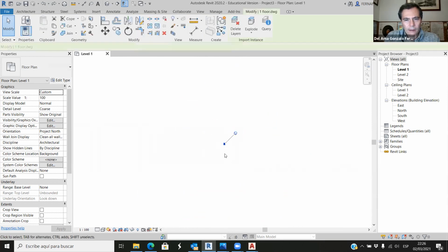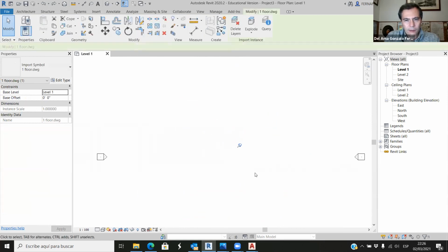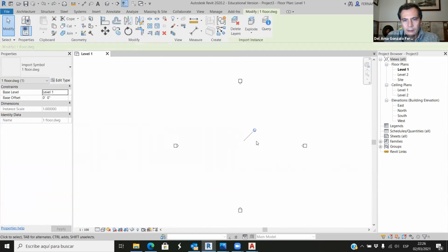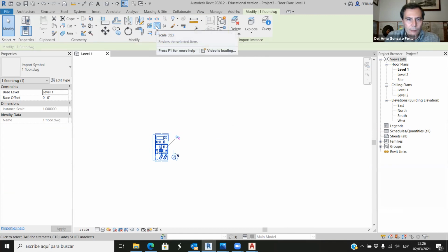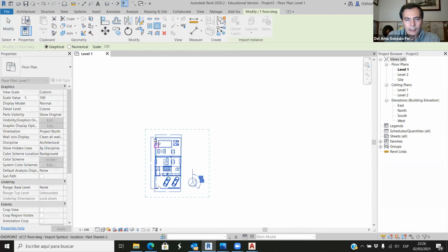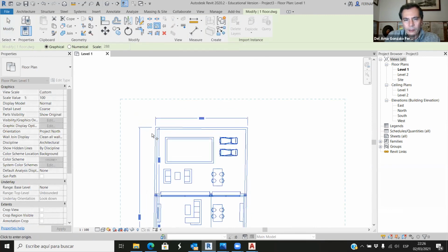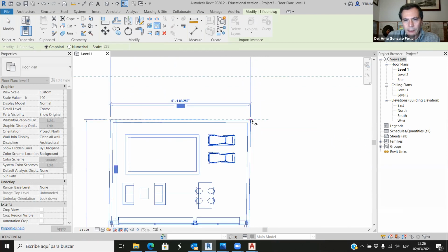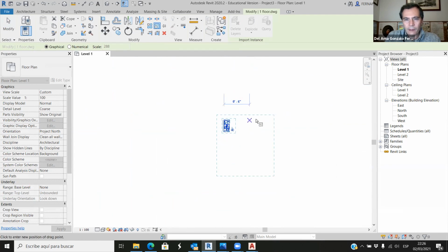Remember that if it's pinned, okay, so first it will be, I don't know, we don't see that. We select this, it's there. We click here. Okay, so it's not pinned anymore. Now we have to select everything. This command, scale. And scale works this way. You have to select the first point, the second point, and then the third point.